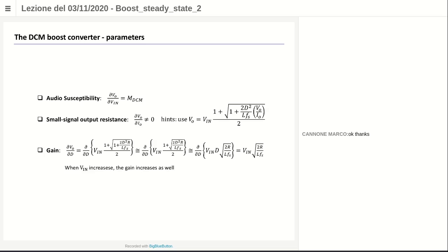If you increase the output power, so if you are increasing the average output current I naught, that means that the electrical stress is even larger. So you can operate your converter in DCM for a given output current, but be sure that your output power is not so large, because increasing the output power, increasing the average output current, brings ever larger electrical stress. So this is not acceptable most of the time.